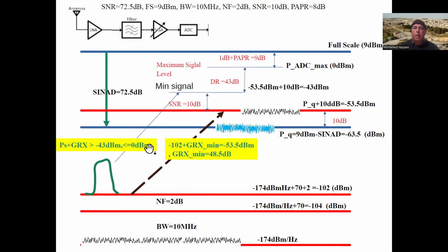And in this case in here, that's the minimum detectable signal. But there's another level, which means you have to go up here, and that means it turns out that you need to reduce the gain. So that's where this AGC sometimes needs to attenuate as well.